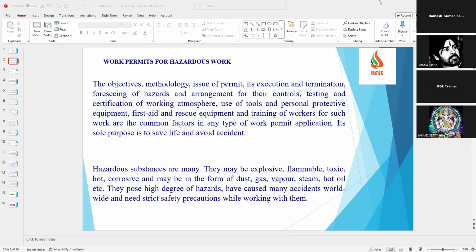As mentioned by Suresh, the permit requester will sometimes be a contractor or a company's own employee. They will write the permit with all the details, then it will go to the respective area owner or area supervisor, and he will give the approval. If any isolations are required, maintenance people will also do the respective isolations, and they will sign with the name and signature of who did the isolation. Then it will go to the safety officer, who will review the conditions.